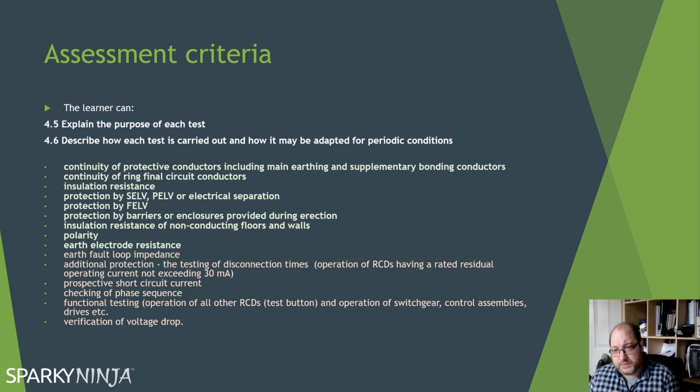So it might be worth just considering those, but fundamentally the idea is to make sure that the value of fault current, be it short circuit or earth fault, has been measured or calculated or enquired, and we then look at the current and we make sure the protective devices that we select and that we introduce at the point, either at the origin or subsequent distribution points, is going to tolerate that energy level.